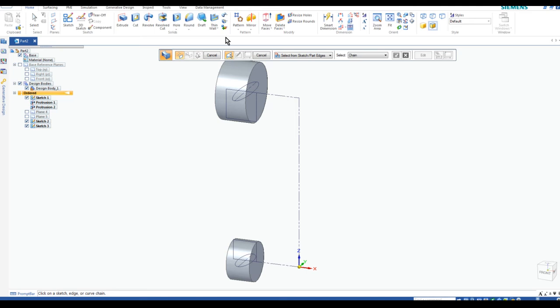Okay. We don't necessarily need to do anything here because it's already set. The only thing you would need to do is make sure that you have select from a sketch as opposed to coincidental or any other option. So I'm going to select from a sketch. It has to be sequential, so that means it doesn't matter which one you pick first, but it has to be sequential. So sequential 1, which would be that one.